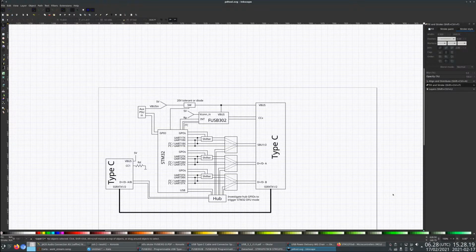Otherwise, it feels like it's going to be complicated to actually use that way if you try to pass through PD and also use it as an interface, because the host might just kill your VBus at any time, and then the whole thing's dead, right? For alternate mode in MITM, that'd be nice, but then you need two PD interfaces, right?